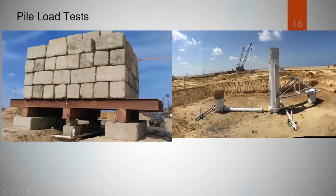These are figures of the site pile tests. This is a compression pile test, and this is a fixed and free lateral test. This is a free pile, and this is the fixed pile. This is a support pile. We make a fixation through this truss to simulate the fixation of the pile head. And this is the jack, and this is a beam to transfer the load from the jack to the free pile head.